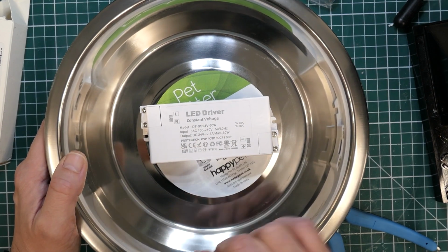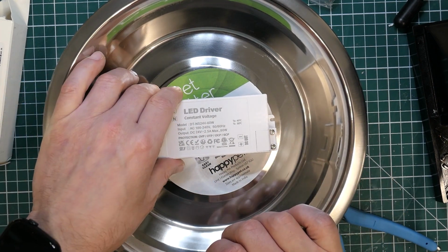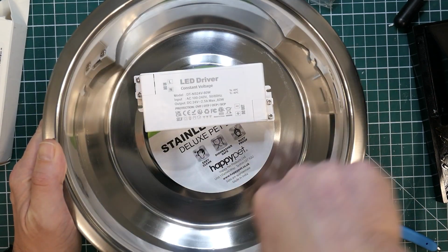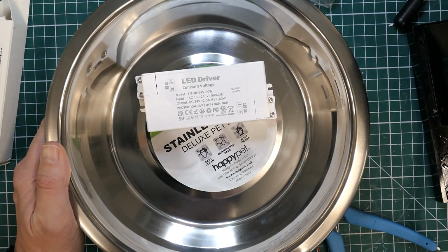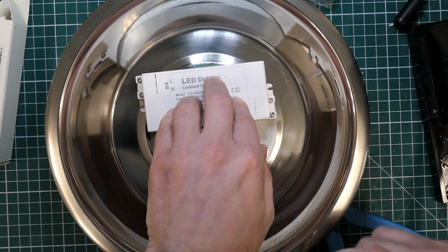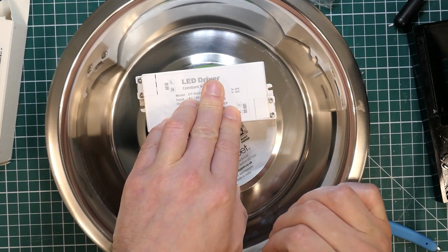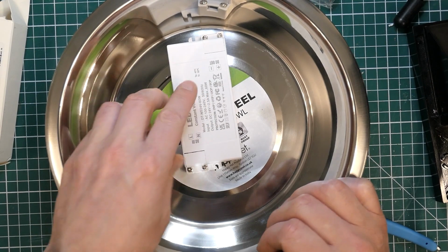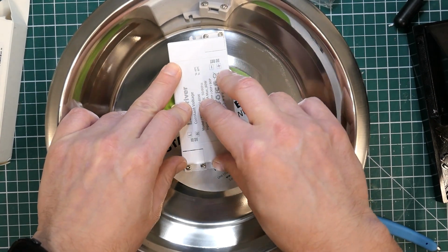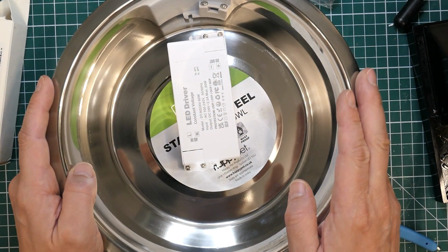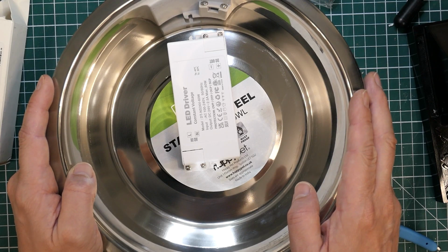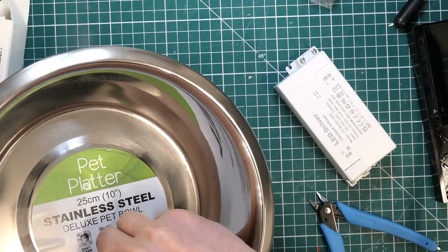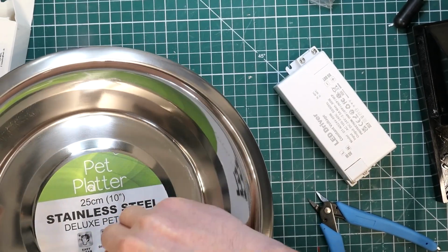I've also showing here the LED driver that I purchased. Again, I got this from Amazon, and it's a 24 volts DC source. So it basically takes in AC mains voltage and gives out 24 volts at 2.5 amps. I initially thought I'd mount that inside the lamp. There's so little space that I'm a little bit hesitant. So in the end, I opted not to put it inside. I mounted it on the outside of the lights in a plastic box, so it's insulated.